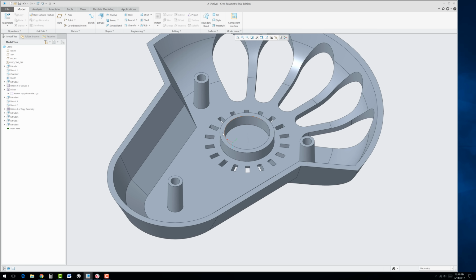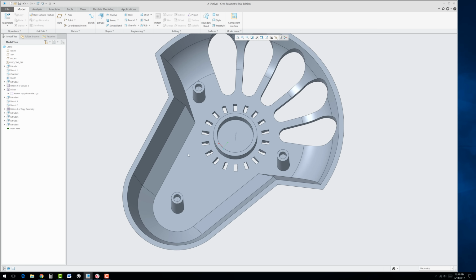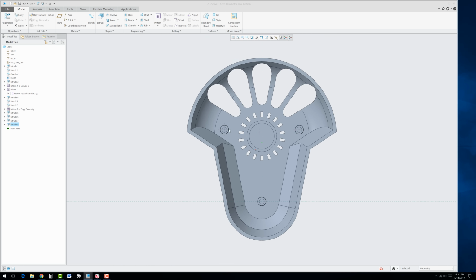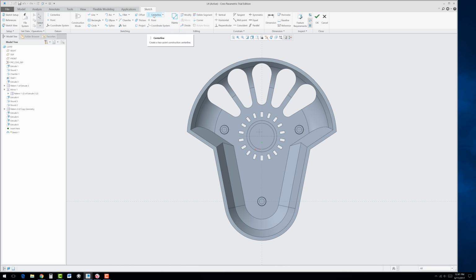If you wanted to put some ribs in here, you could do that as well. What I would recommend here is actually use the floor of this pocket, and we'll go ahead and create. Okay, and so from here, you could select this face, and don't go to extrude. You could actually just go right to sketch, and you could sketch the ribs in however you would prefer. We could go in here, like for example, I could draw this out, and maybe we might want to make a parallel to that. See, I could wake up that edge. Now I got parallelism. Could do the same over here. I could mirror too, but this is just good practice.